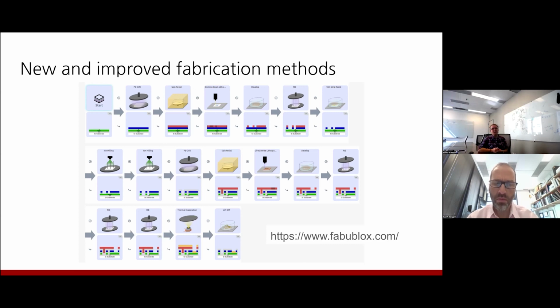After we mill the sidewalls, we're re-encapsulating it with silicon nitride, which again, as we established with STEM, is going to result in very little diffusion into the film that could damage it. I've put ion milling here in this particular iteration, but we've also been exploring ways that we can do the pattern transfer using the RIE-ICP tool, which is nice because that would allow us to do everything in the clean room. It's also a load-locked tool, and if you have some chemistry involved, you have a little bit more ability to determine the selectivity.